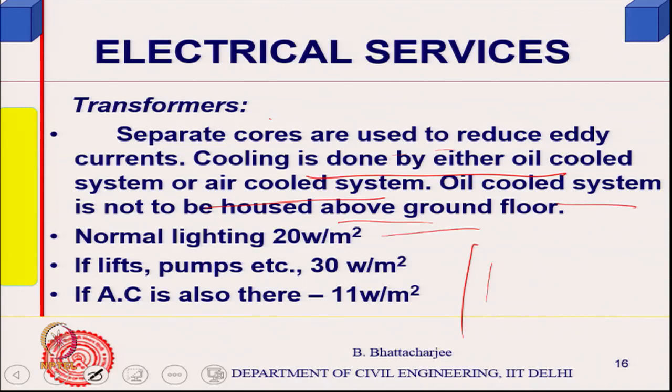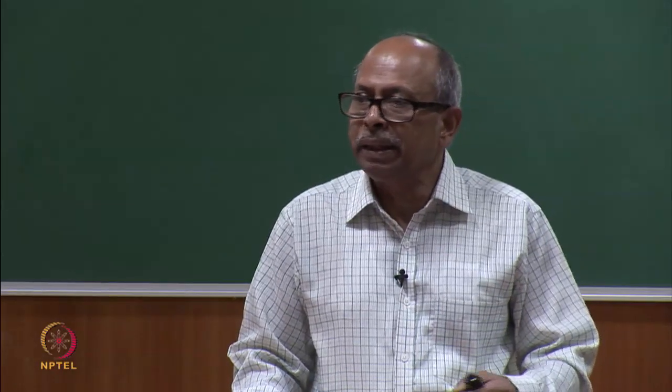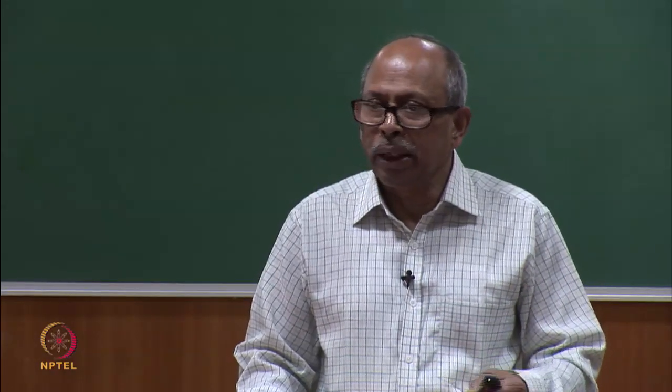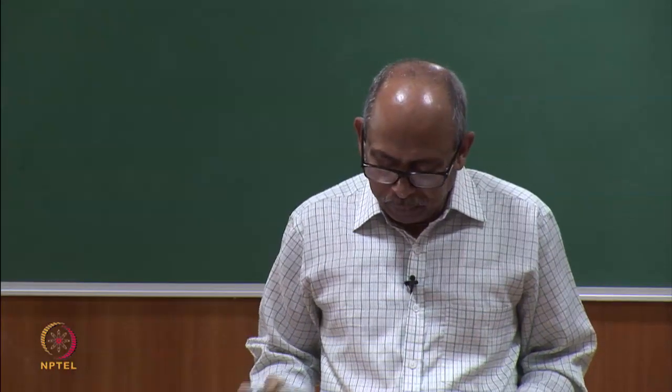Oil cooled systems are not housed above ground floor. Air cooled systems are more efficient, and with oil cooled there can be fire hazard and those kinds of things. So they are not actually preferred. So that's the kind of safety guidelines that are there.